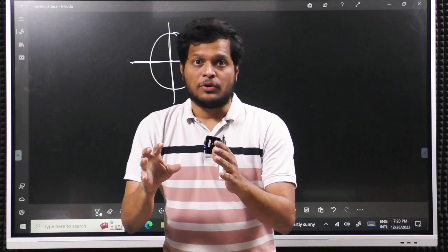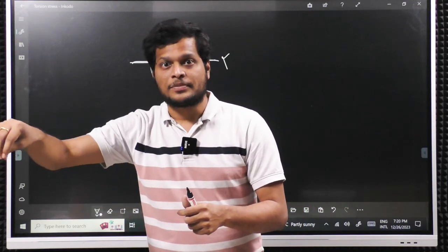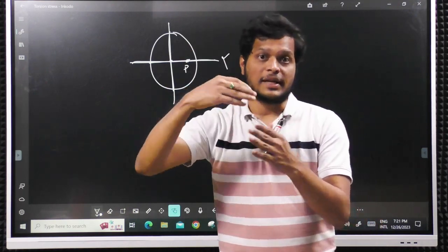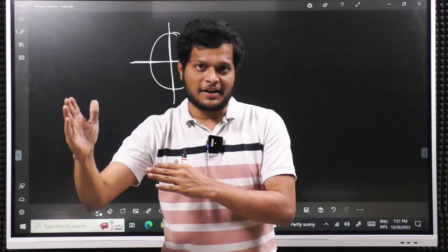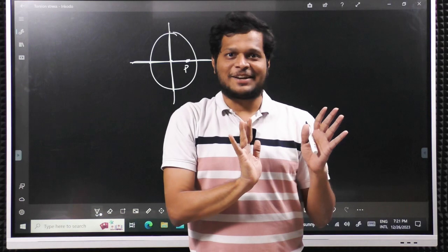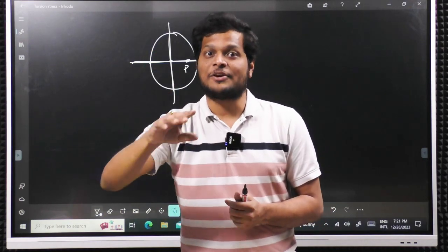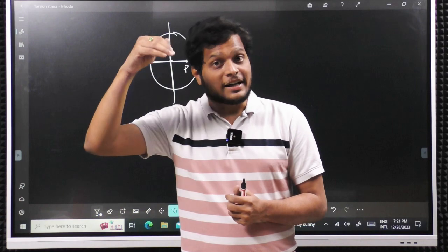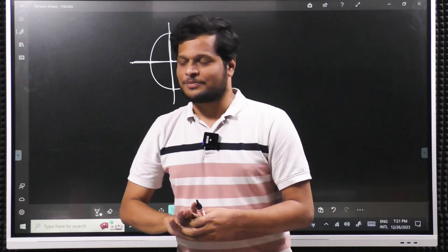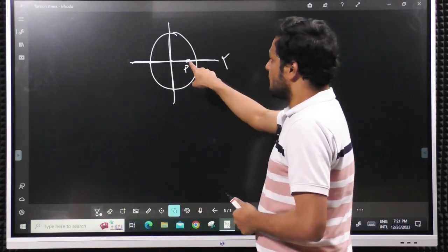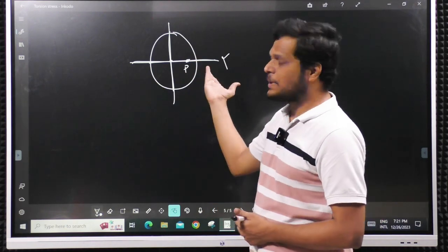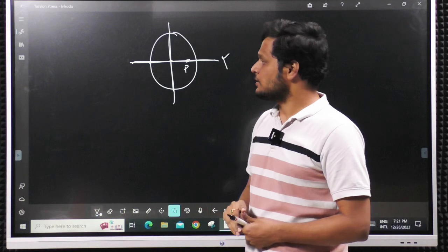That is for the load applied on the column directly, I am telling you. If you apply the load on the slab, which generates a couple, and the couple is applied directly on the column, then there is a possibility of creating torsion. That is secondary. I am not saying that because of gravity you cannot get it; you can get it indirectly from the slab. The slab can transfer it. That case also I will show you. So directly by applying the gravity load on the column, you cannot get torsion because it is parallel. But because of wind load you can get the torsion.